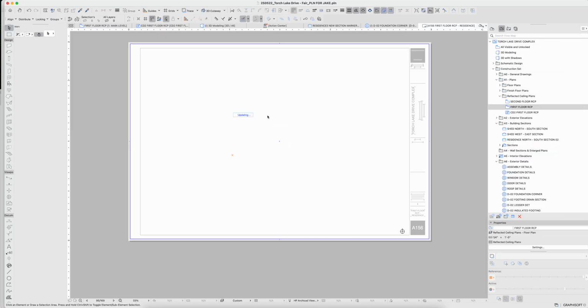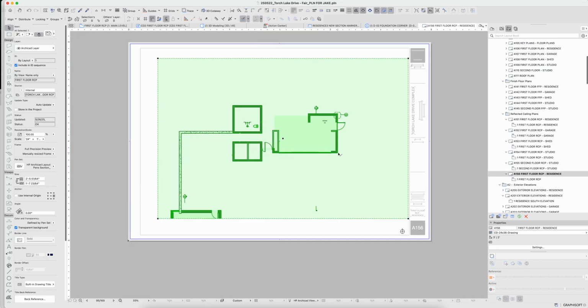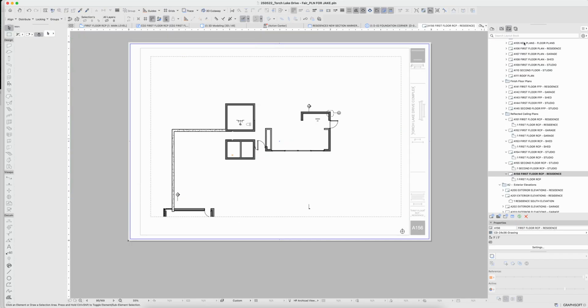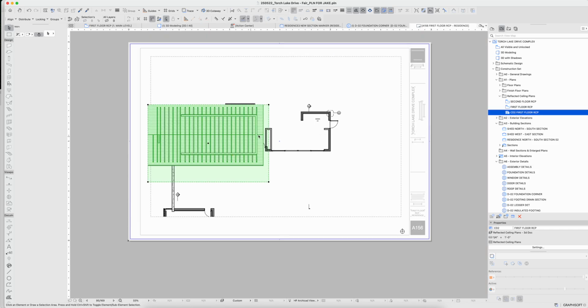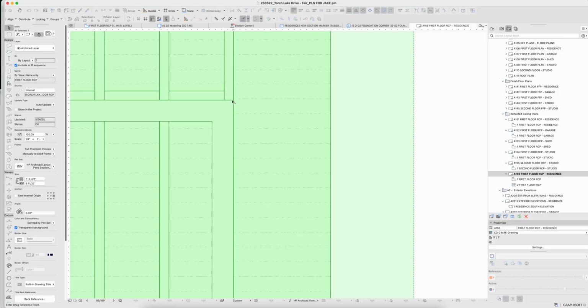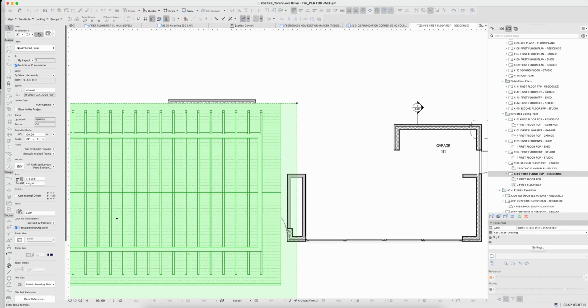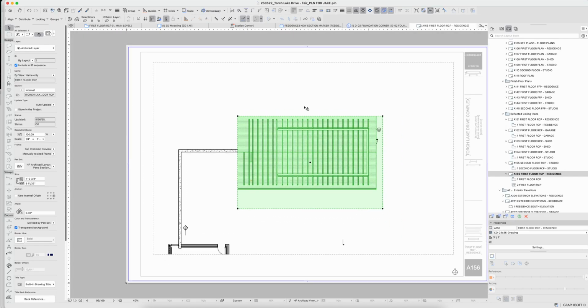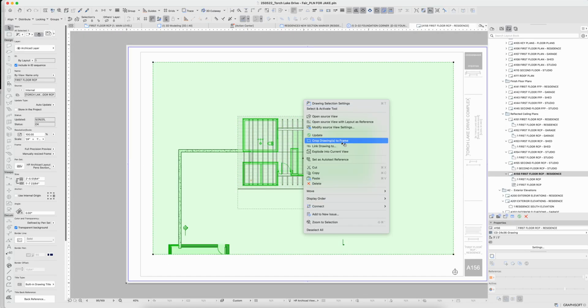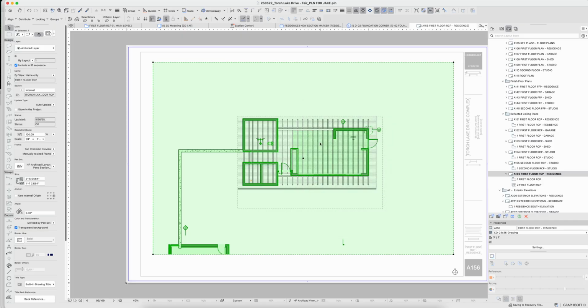So we drag the first floor plan over. There's the floor plan. And then we drag our 3D document over. It can be a little bit tricky to align these things if you don't know where they're supposed to align to. So the grids or columns or some common layer that they might have together. Now, let's go display order and bring the floor plan to the front.